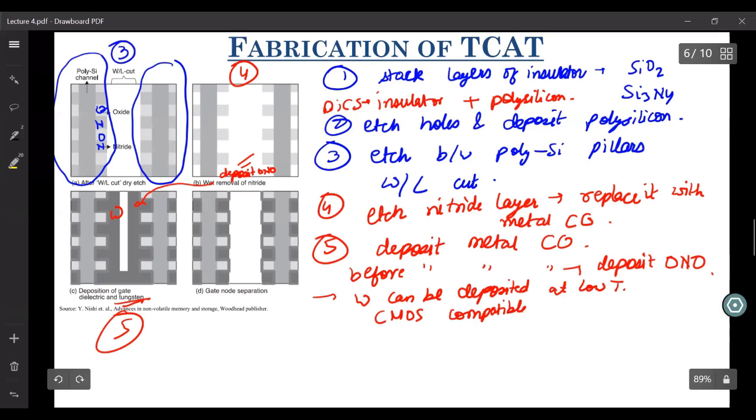You may have read that it provides good adhesion with the underlying substrate. So this is used for your source drain contact plugs, and then on top of this you use titanium nitride. That is why you use tungsten. It can flow easily at low temperatures, and it is CMOS compatible.